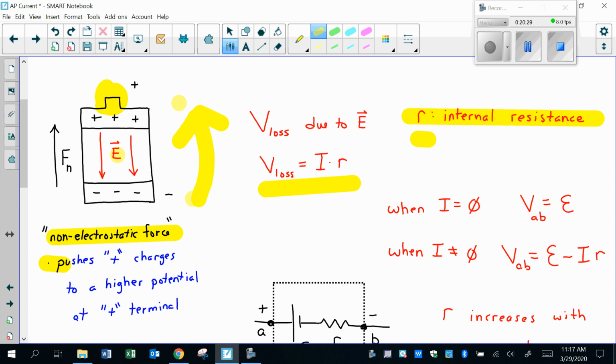Until today, we only cared about the end result. All we cared about was the output. How we got that output didn't matter to us. Well, what was happening is inside you got something doing the work, pushing the charge where you want it to go, but there's also some resistance that it has to encounter. When you have no current, you have no resistance loss. V equals I times R. If there is no I, there is no V that is lost right here. There is no V that is lost.